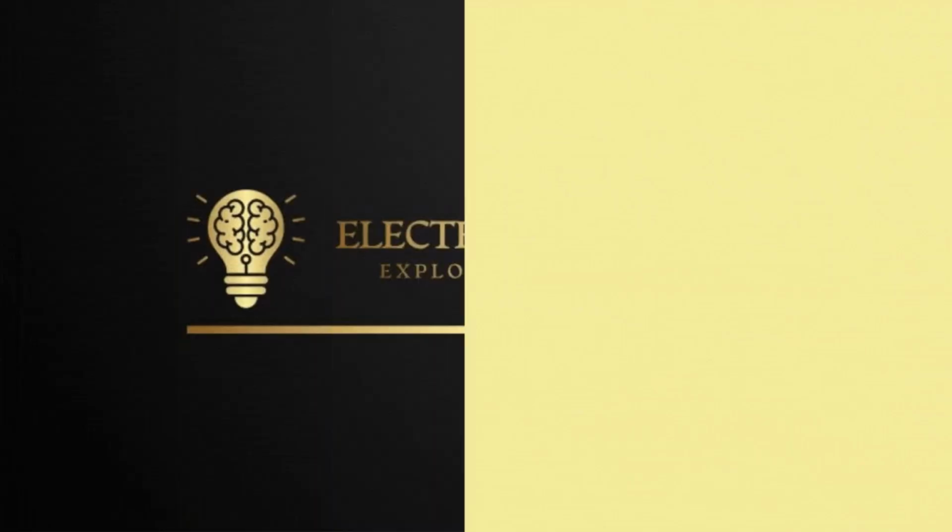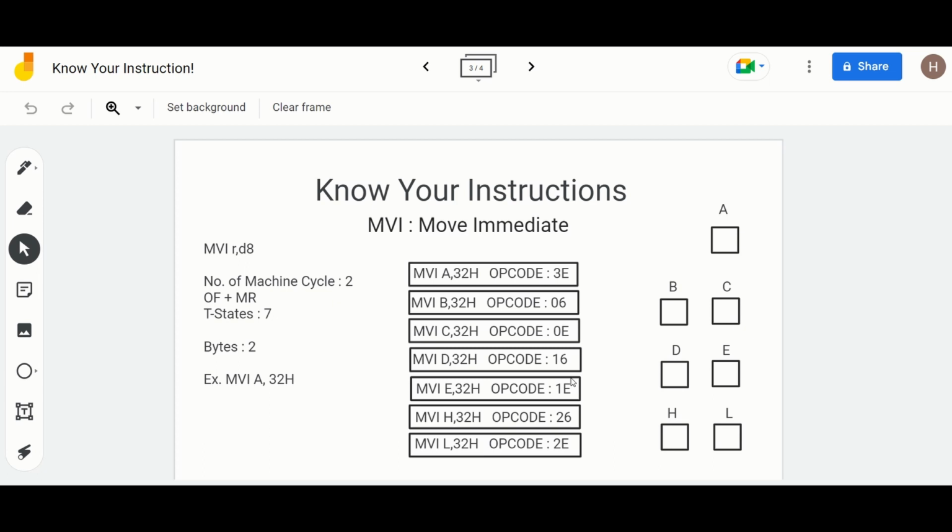So let's begin. First of all, MVI stands for move immediate. If you want to move your data immediately to a register, we will use MVI R,D8, as you can see here. This R stands for register and this D8 stands for 8-bit data. For example, I want to store 32 in my accumulator. My accumulator is also a register. So what will I write? I will write MVI A, 32H.